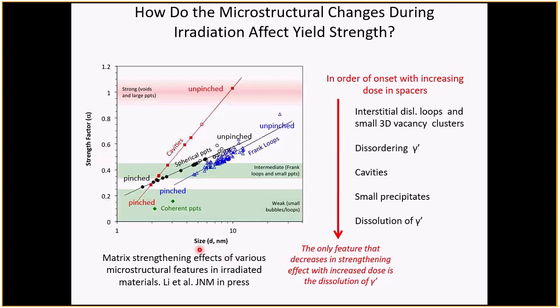In this case, we're not considering the effect of thermal aging, as when we discussed precipitates, and how when you age an alloy and you're doing some precipitation aging, the precipitates get bigger. When they get bigger, they're also getting further apart.